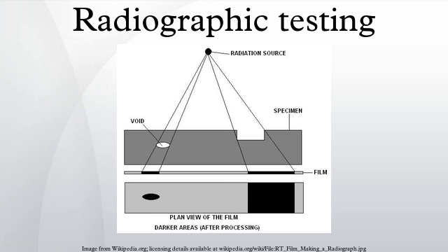The specimen to be inspected is placed between the source of radiation and the detecting device, usually the film in a light tight holder or cassette, and the radiation is allowed to penetrate the part for the required length of time to be adequately recorded. The result is a two-dimensional projection of the part onto the film, producing a latent image of varying densities according to the amount of radiation reaching each area. It is known as a radiograph, as distinct from a photograph produced by light.